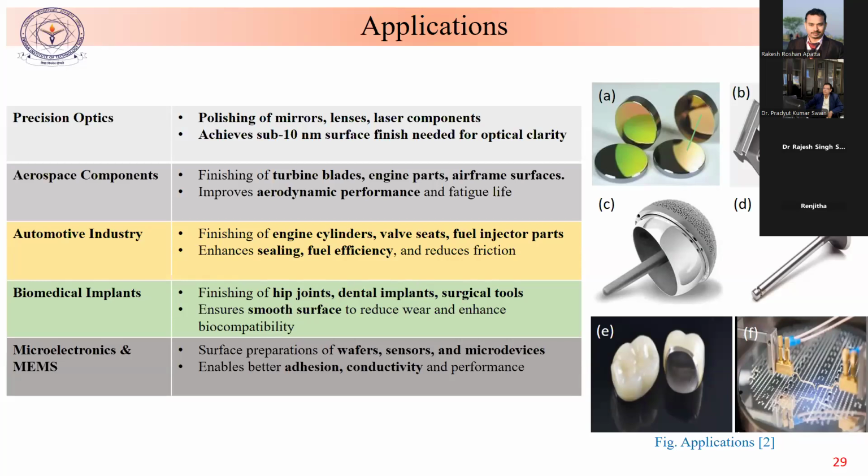And the tools we are using have a diameter of around 100 or 200 micron. 100 micron is about the diameter of your hair. Sometimes less than that, because we have used micro milling tools having a diameter around 80, 70 micron. Less than that, till now, we have not manufactured, because it does not sustain the machining.